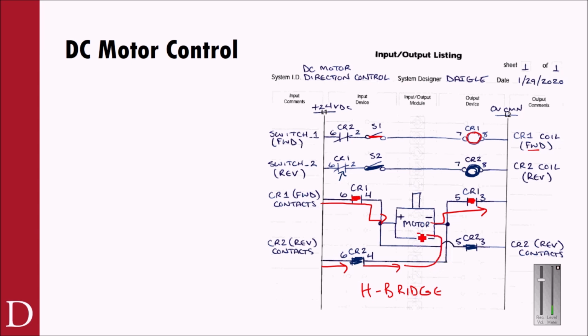I go up and I go through in this direction, and then I go down and through CR3. So you can see that the motor direction changed from this direction to that direction. And whether you call it forward or reverse, clockwise or counterclockwise, doesn't matter as long as you use it the way you want to use it, like we did on the elevator control.